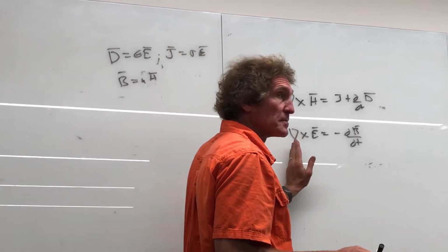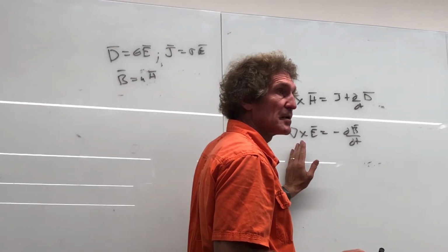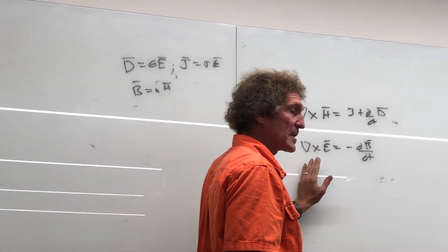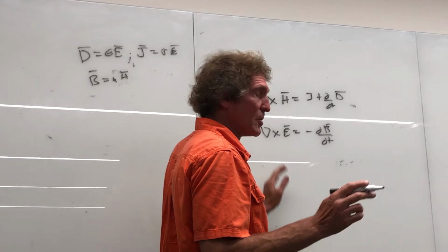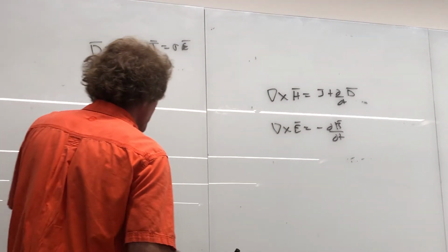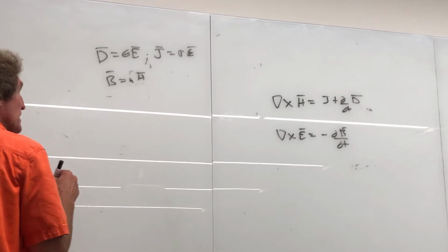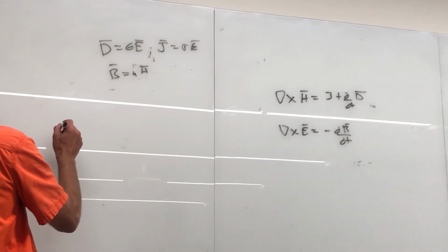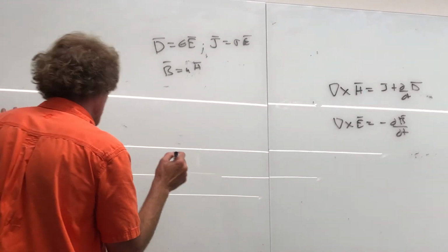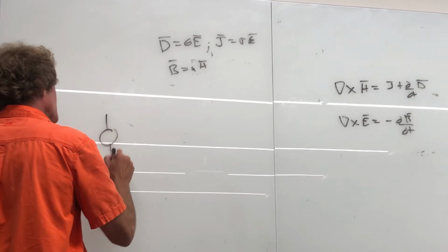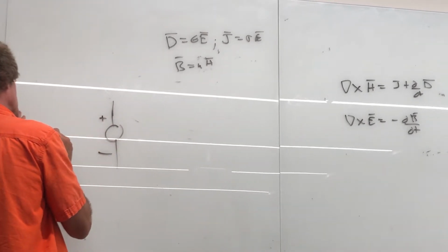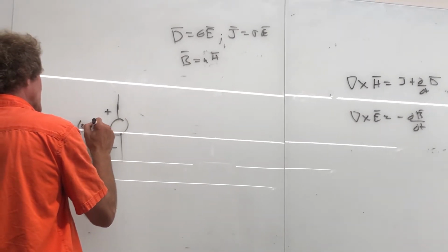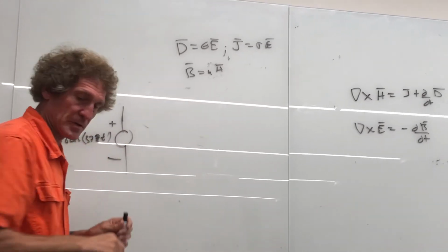Now, when we take a look at these, normally the first thing that's done when we want to look at the effects of propagating electromagnetic energy is that we go into the phasor domain, and we'll also eliminate some of the confusion by only solving for two variables, which will be H and E. So I have to first say this, and I always do this to my classes. Normally when you see a circuits problem, if you have plus or minus, say, V0 cosine of 377t, right?